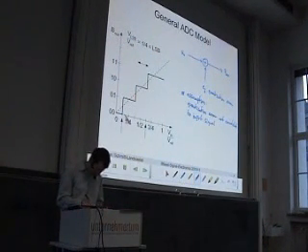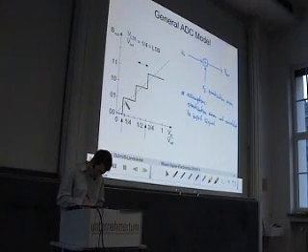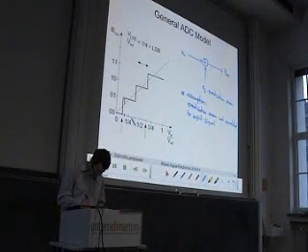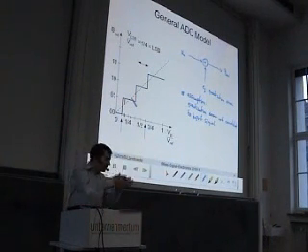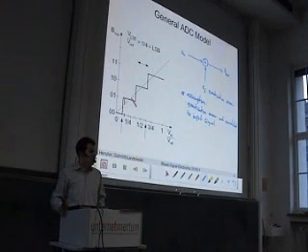This is not true, because if we say, for instance, we have this input signal, then the quantization error is exactly this one. Or if we say this is our input signal, then the quantization error is exactly this one. So for each input voltage we have a given quantization error.